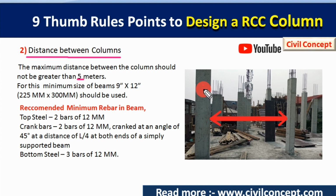You can see here this is our column, and the distance between them should not be greater than 5 meters, or if we convert it into feet, it may be up to 16 feet. So we should provide a distance between two columns of less than 16 feet. Now the recommended minimum rebar in the beam: if the distance between the columns is up to 5 meters, then we can provide top steel of minimum 2 bars.